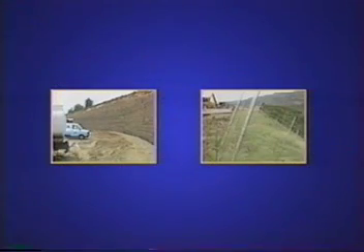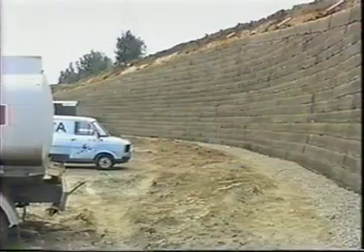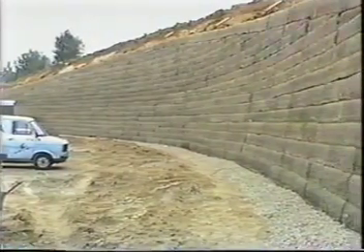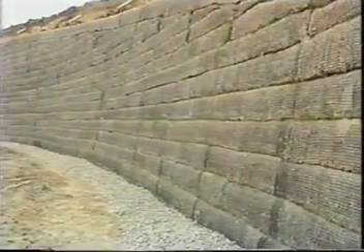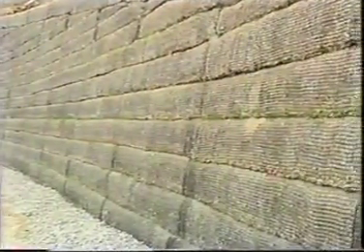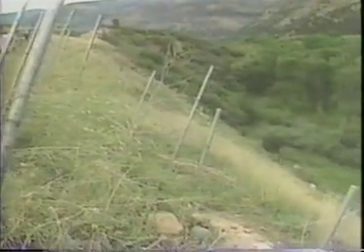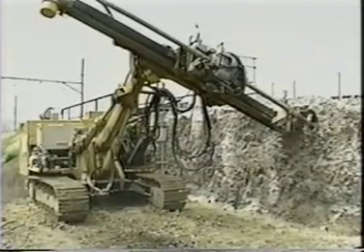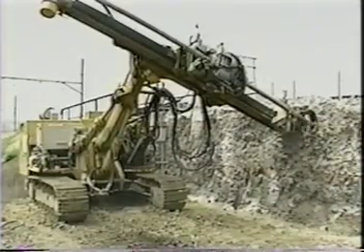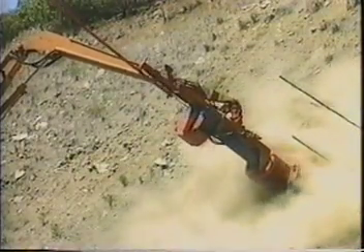There are 2 distinct technologies for reinforcing soil: reinforced fill and reinforced ground. Reinforced fill is engineered fill incorporating discrete layers of soil reinforcement between successive layers of selected fill. By contrast, reinforced ground is natural ground or pre-existing fill reinforced by soil nails. The nails can be inserted by various techniques such as drilling and grouting, or by ballistic insertion, in which nails are fired into the ground.